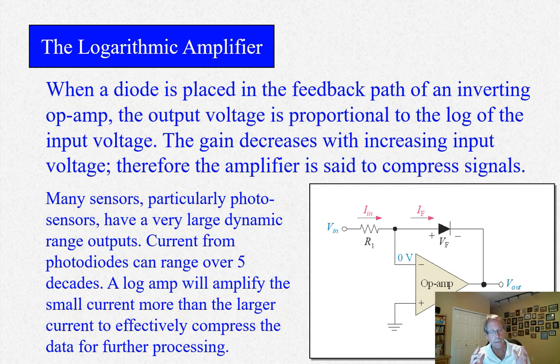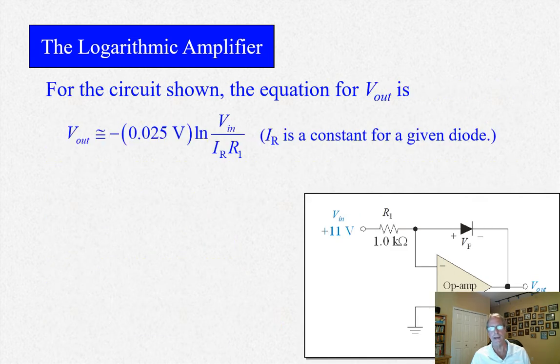Now, if you just put a regular amplifier in there, think about that. Oh, why don't I just multiply everything by 1,000? Okay, that'll work great for when the signal's really low, like down in the tens or hundreds. But as soon as the signal starts getting higher, up into 1,000 and 10,000, you're going to saturate your amplifier. You haven't got that much dynamic range, so you have to compress that dynamic range, and that's what a log amplifier does. Now, how do you put it back? Well, we'll look at that in a minute here.